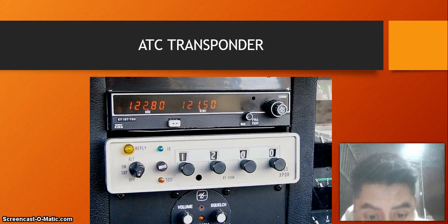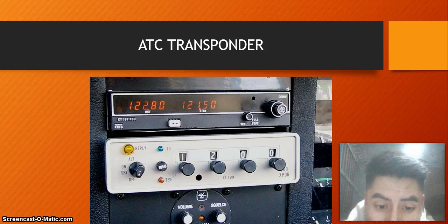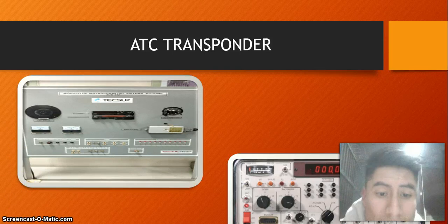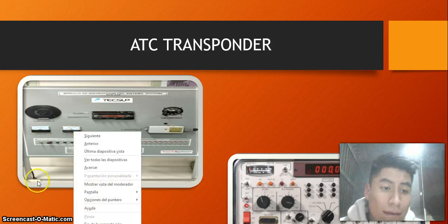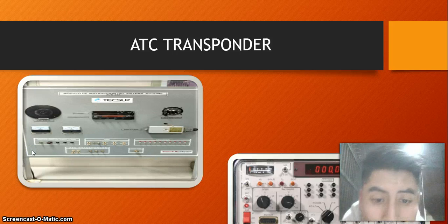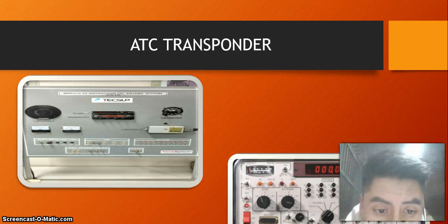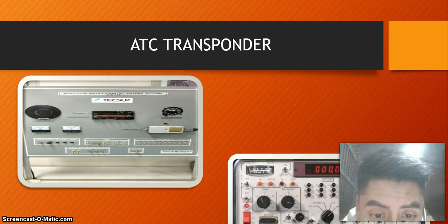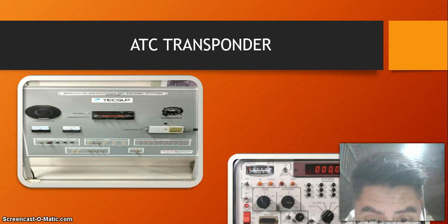To perform the operational test of this system, it was necessary to use the following equipment and components. First, we have a test bench ABS34. In this module, you can simulate the altitude using the encoder system that works in gray code. This code is used mainly in the position system. It is for this reason that this code is fundamental to insert the altitude. When manipulating the manual switches, the transponder immediately afterwards sends the selected altitude.